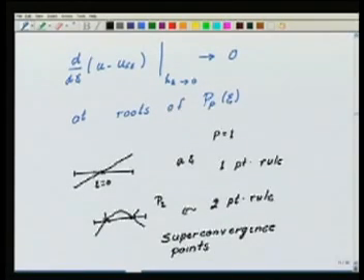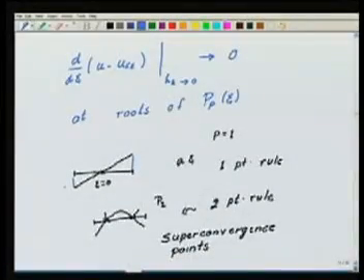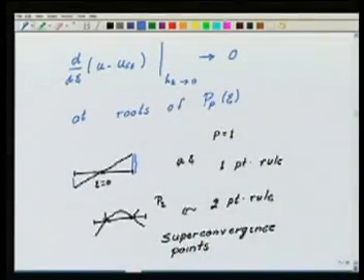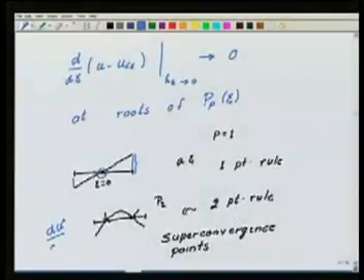Okay, so if I have obtained superconvergence points, there is another thing you should look at: at the nodes, that is at the extremities of the element, the derivative obtained from the finite element solution is the worst. It is the worst that I can get. In fact, I should try not to use that information. So, how can I use the information about these good values of the derivative of the finite element solution to obtain a better approximation of the derivative? Okay, by some post processing.